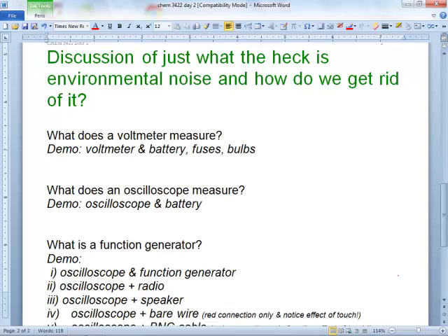Oh, that's off scale. Let's see. See what I'm doing? I've just got to play around with this until I get it to work. Where's position? I need it. Oh, there it is. Let's see. So flat line. DC volts. Okay. And if we would have been careful, we would have seen it jump up 9 volts. If we could watch the boxes and see what the voltage is per division, it would have jumped up 9 volts.